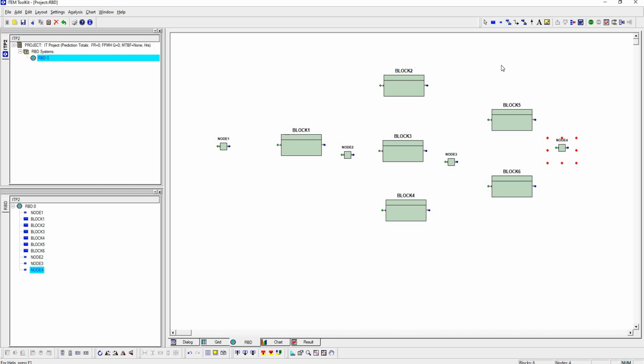on our design. To do this, we would select our preferred type of connection, whether a straight line or right-angled lines with arrows, etc. It is entirely up to the user. Let's select the right angle connections with an arrow indicating the direction of the flow. Now we can start to connect our nodes and blocks by simply left mouse clicking once on the output node of the node or block and the input node of the node or the block. We do not need to click and hold to drag. We simply do a single click and move the mouse followed by another click.